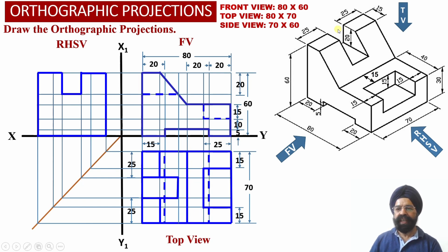So we can check, this is a bigger inclined surface which is available with us in the isometric projections, but since the surface happens to be inclined with respect to the horizontal plane, in the top view projections we have been able to obtain a foreshortened, reduced or apparent shape projection over here. Now we have been able to complete the top view projections corresponding to this engineering object.